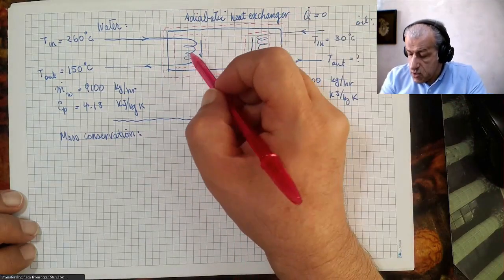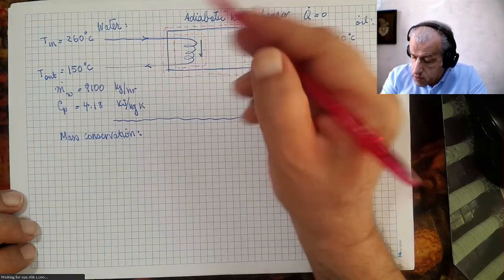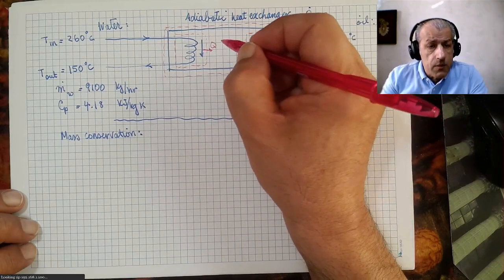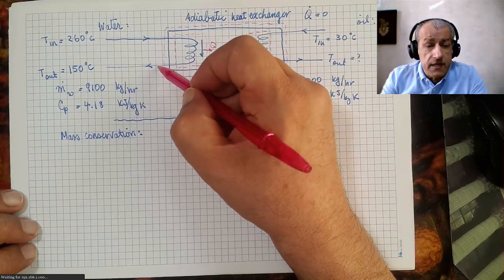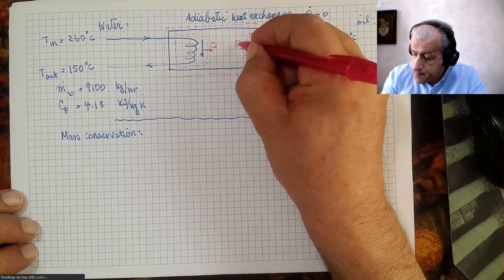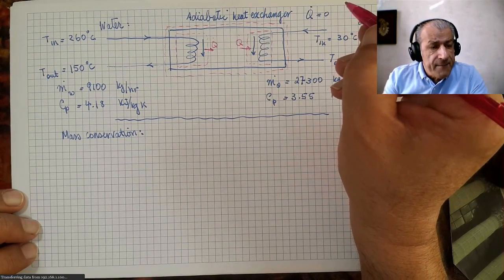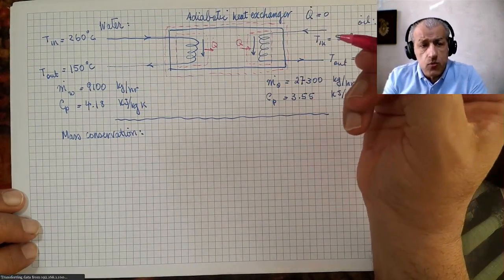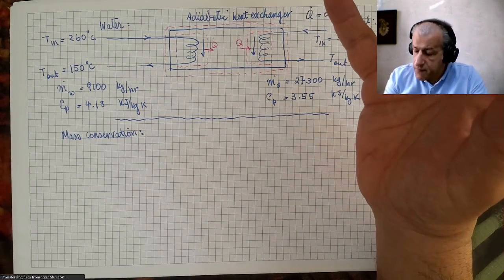Look, this control volume is water. It is warmer, so we know that it loses heat. There is no work because there is no moving boundary. There is mass in and mass out, and it is steady. This control volume receives heat, and there is mass in, mass out. There's no work since there's no moving boundary, and therefore it is steady flow.